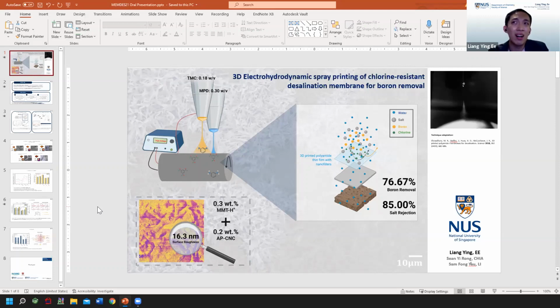One strategy is using various surfactants on the UF substrate that help our monomeric layers to be tightly sprayed onto the membrane layer itself. As you can see in this case, we only require 2 scans of the printing to achieve 85% salt rejection.